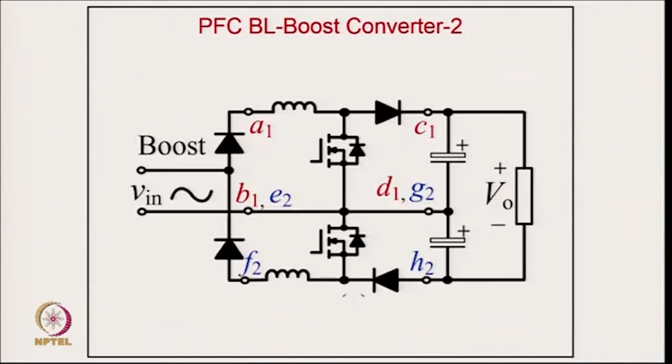Of course, you have to use two devices, and this is the circuit for the positive half cycle and then the negative half cycle. You can understand that in some applications we require two equal voltages. Of course, it is one load here, but sometimes you require two equal voltages with power factor correction, like a switched reluctance motor drive of 4 phase, where you require a midpoint. So, that can give you a midpoint also for some applications.